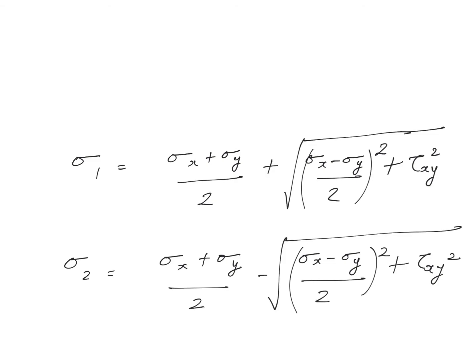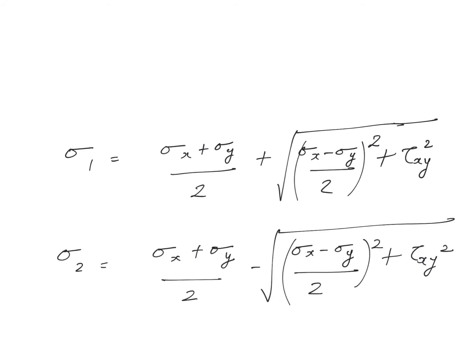I would like to show you the expression for the principal stresses. This is something you should know because in exams I have seen these people ask questions where you need to invoke these equations and plug in these numbers. One bit of information is this quantity is the radius of the Mohr circle, and this is the x coordinate of the center. That's one way how you can remember this expression rather than just simply mugging it up.